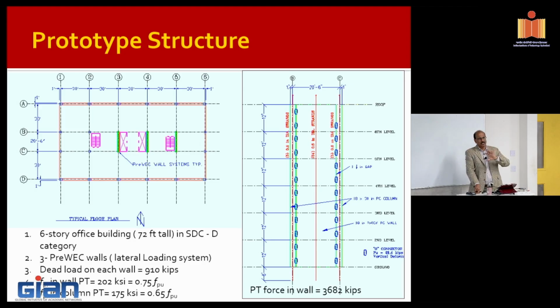The reason I want to compare and contrast the two systems here is that if you can rely on the other system, you can actually use that for non-seismic applications, right? For non-seismic applications, 5-8% damping is more than enough. That's what we don't calculate, we don't design, so there's no reason to do it. So we wanted to influence. If you have more walls in this structure, say gravity-bearing walls, they could be designed as post-tensioned, unbonded, just let it go for the ride. Don't do anything, because it's cheaper to do it that way.